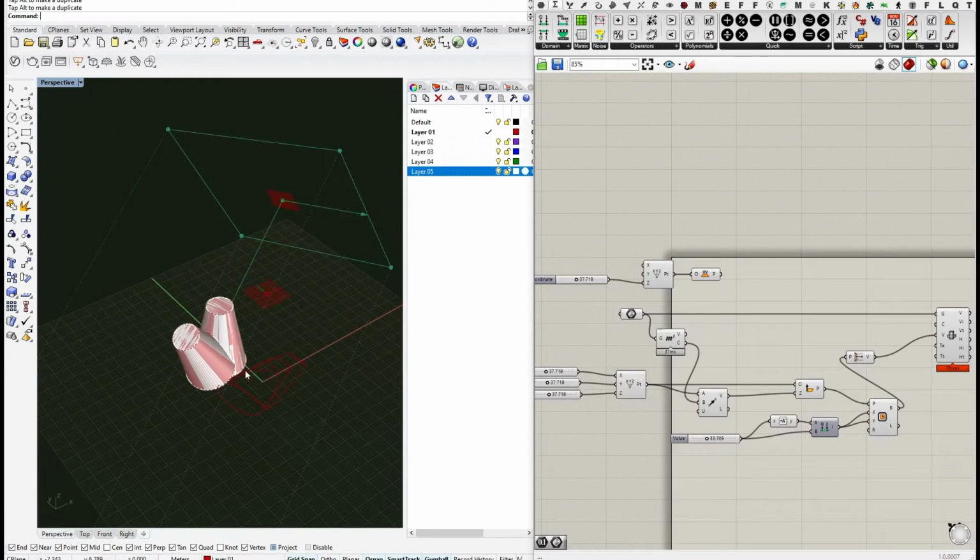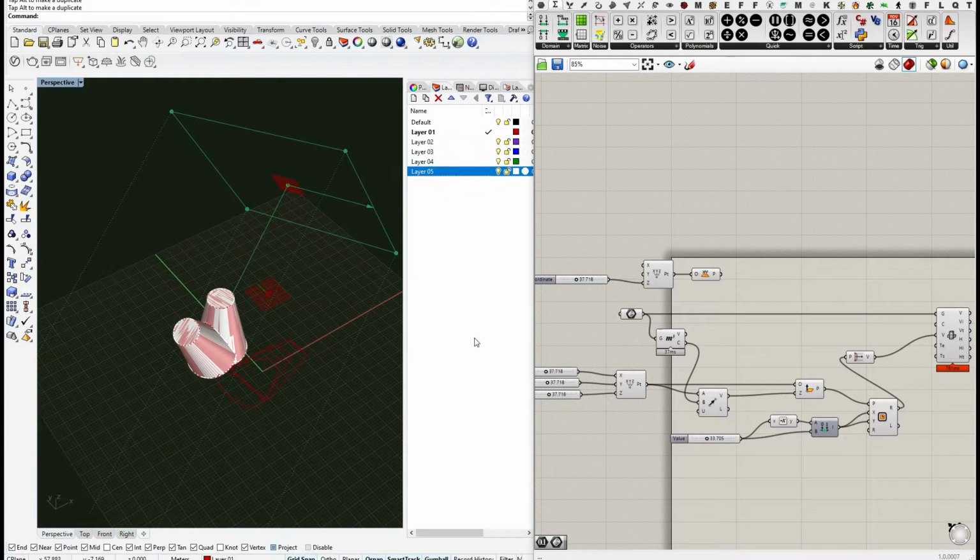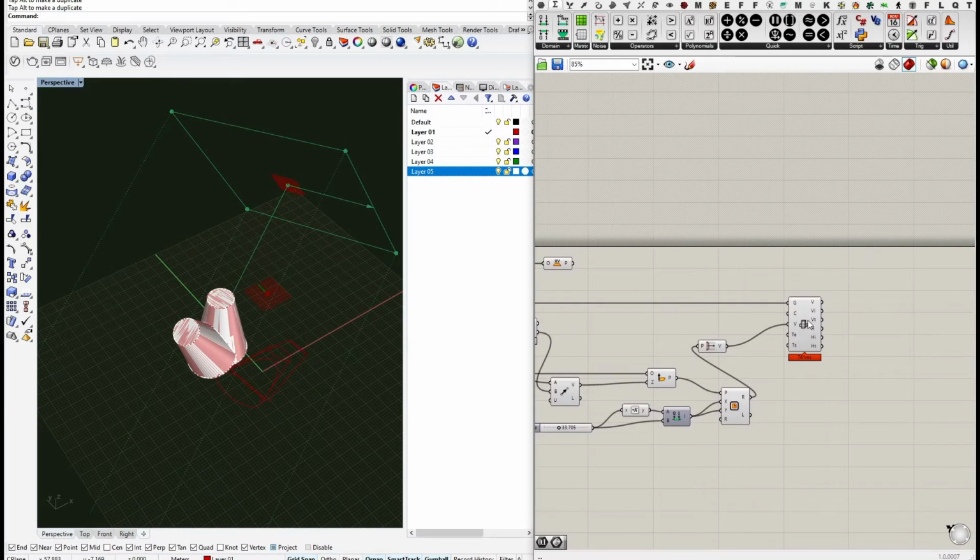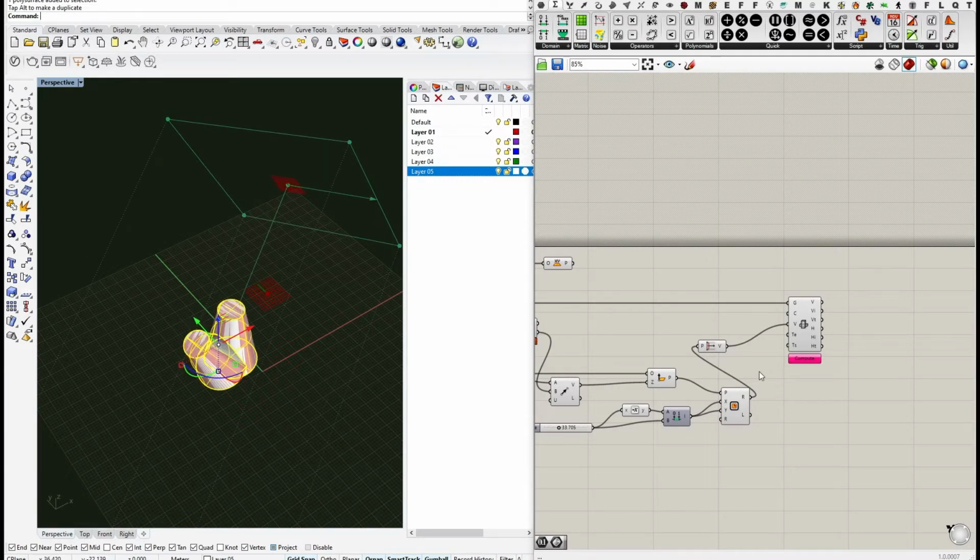Now, this might be good for animations, or if you have very simple geometries. If you have very complex geometries where each Make2D calculation step might take a long time, I would advise to turn the automatic off, so that every time there is a change in your geometry, you compute it separately.